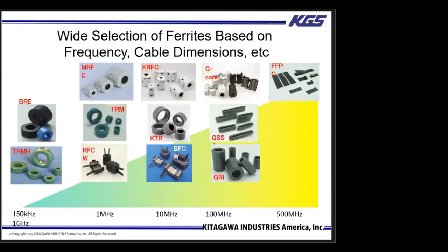Just to add and clarify a little bit, we have an upper limit on our ferrites because after a certain point, it gets too hot for the ferrite to function. That's why we generally limit it to about 125. We're currently developing those for about 150, but right now 125 is the highest.